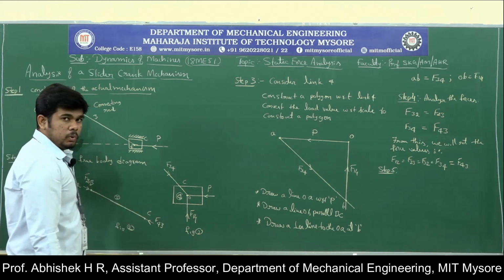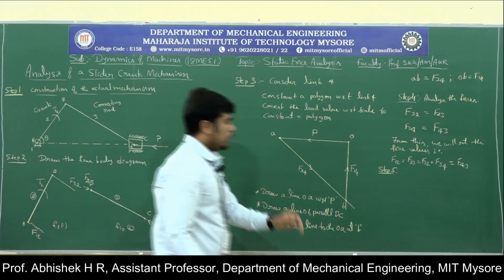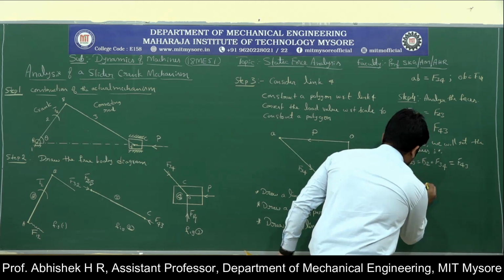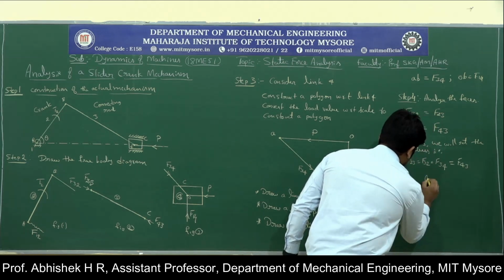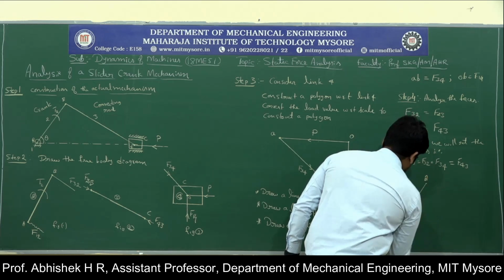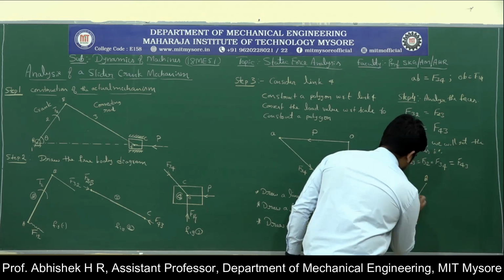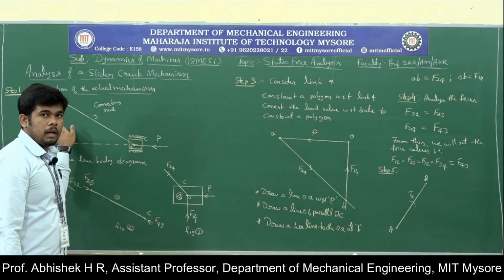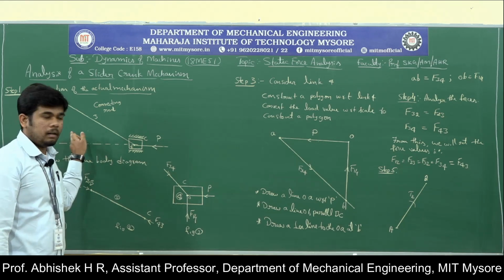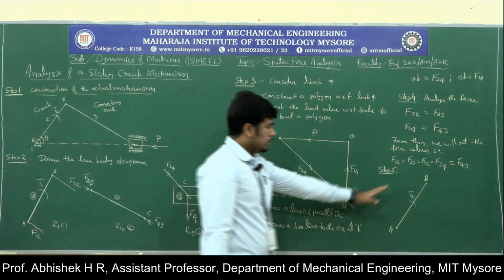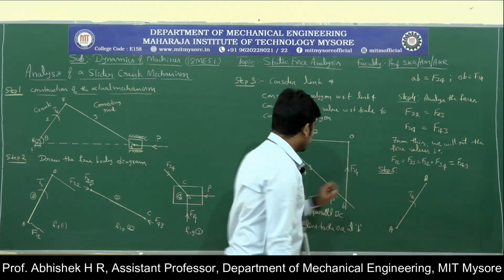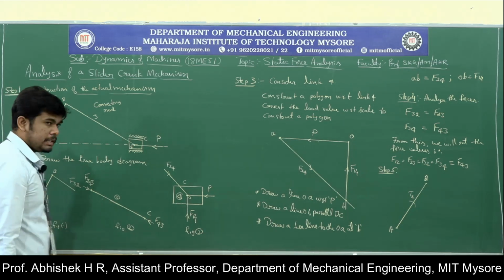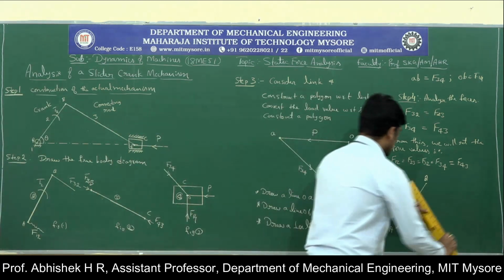So parallel to link 2, that is AB, draw this once again. Use the given distance and also the required angle, and parallel to that draw a line. Now for link 2, one more link is attached, that is link 3, as well as the force F12.